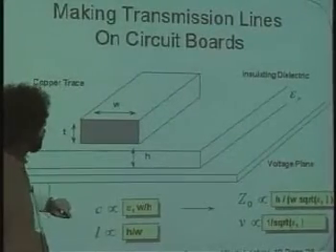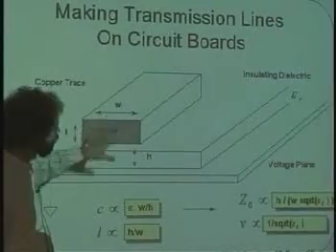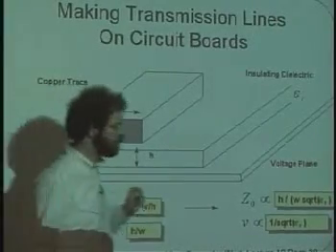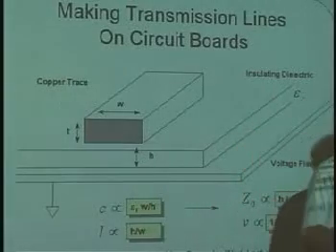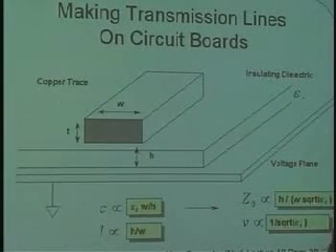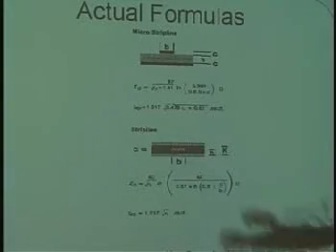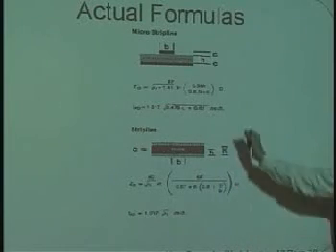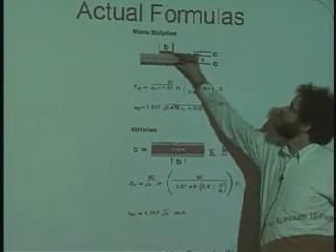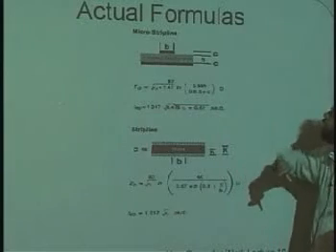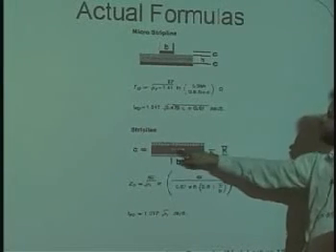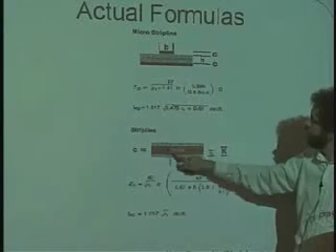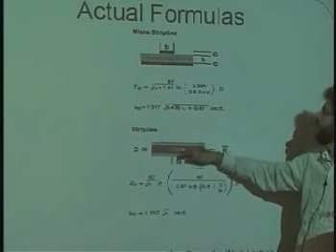Okay, and it turns out that if you care about these things, the equations for exactly figuring out what the capacitance and the inductance of wires that are set up like this are given in the next slide, which you can barely even read, but they have to do with how wide the wire is, what the height of the insulator is, and sometimes we actually even bury the wire in between, inside of an insulator like so, in between two ground planes like this.